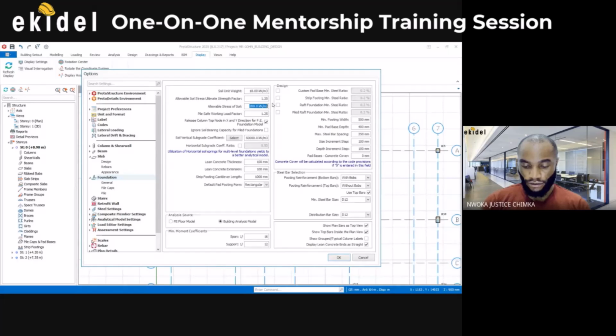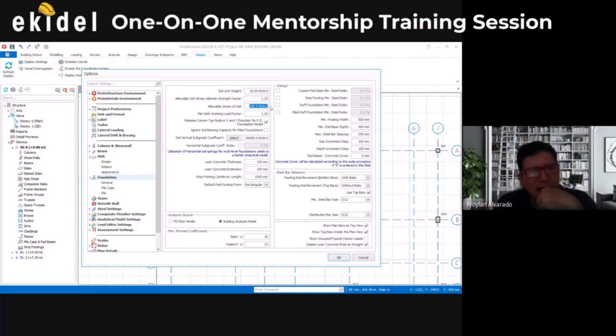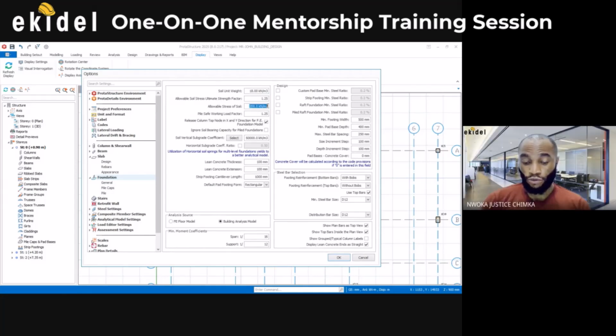Then footing pressure 200 kPa. So the bearing capacity I'm seeing here, allowable soil stress, is 200 kilonewton per meter square. That's 200 kPa, which is about 4,000 PSF.